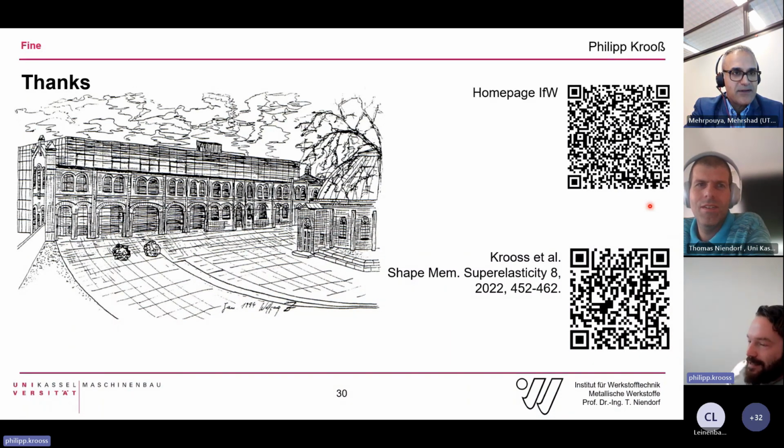But since I know both processes, I would suggest that the high temperature in the EBM process, so 920 degrees C in our case, is beneficial for printing shape memory alloys. The microstructure changes significantly, and I think this high temperature opens up a possibility of printing hard-to-print materials. So I think the formation of cracks, for example, is less of an issue in electron beam melting than in LPBF. And this is one big advantage of this process, although it's a bit more complicated.